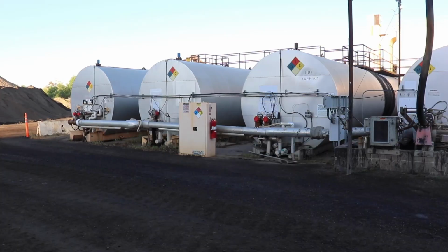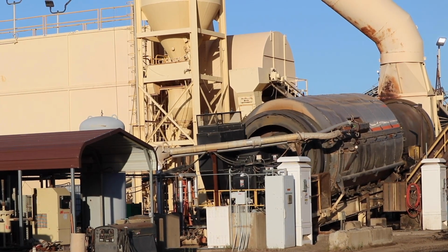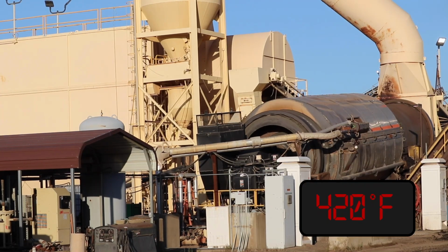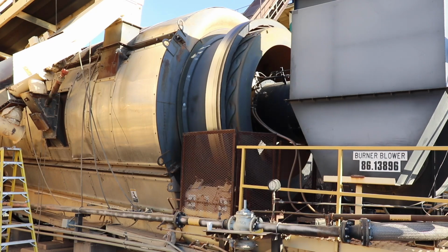Other storage tanks contain the extender oils and anti-strip agents. Please note that polymers are not currently used in high-viscosity RAC mixes. The heat tank is required to raise the asphalt cement to a range of 400 to 425 degrees Fahrenheit. The blending unit is where crumb rubber is blended with the elevated hot performance graded, or PG, binder. Once thoroughly blended, these materials are then pumped into the reaction vessel. The blended mix typically contains 18 to 22% crumb rubber with particle sizes ranging from number 8 to number 10 top size and can include extender oils and other additives such as anti-strip agents.